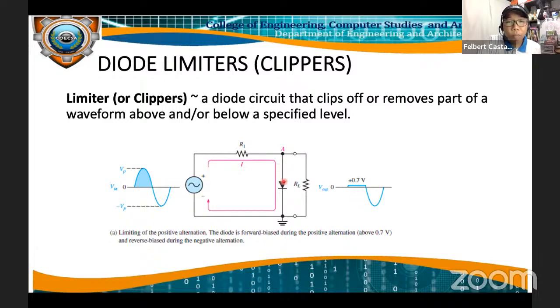As you can see, kapag positive half cycle, ibig sabihin positive yung voltage natin. So what will happen to the diode? Will it conduct current or not? Ganitong case na yung input natin is V positive, V peak or VP, yung diode is in forward bias na condition.